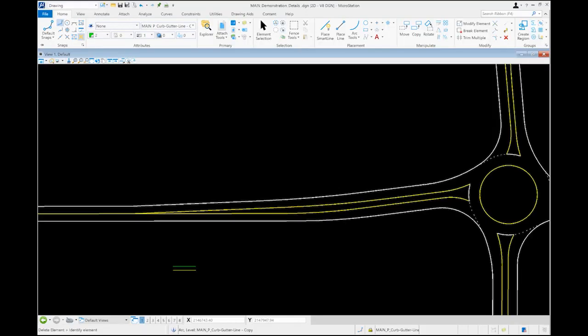In this exercise, we will further add horizontal design details, including the splitter island, curb and gutter, pedestrian crossing, sidewalks, bike features, and assess the truck apron width needs based upon the design vehicle swept paths. We're going to start by laying out the splitter island for this west leg as one example. The splitter island supports vehicle channelization and speed control through the entry and exit.